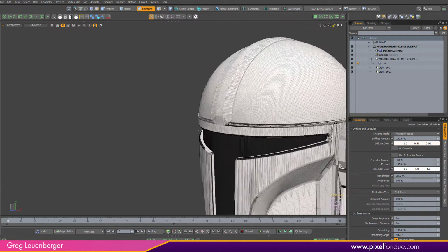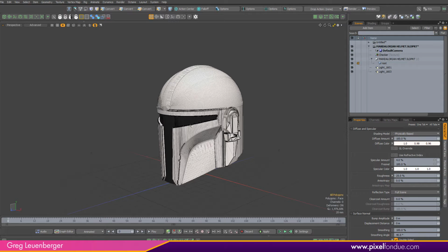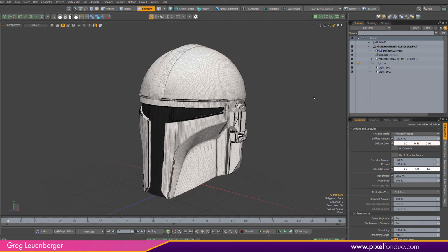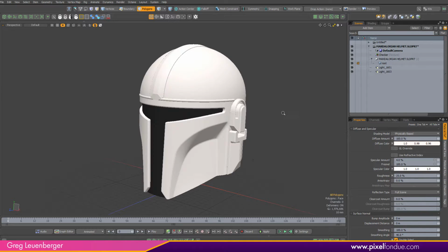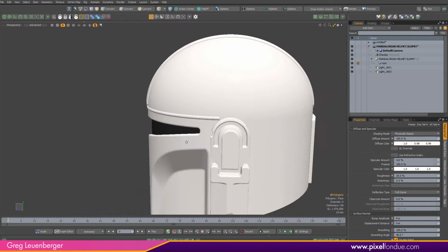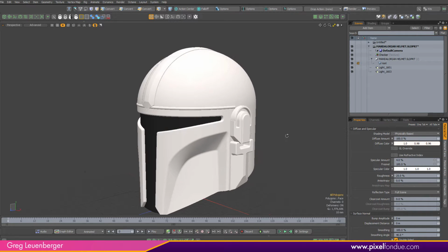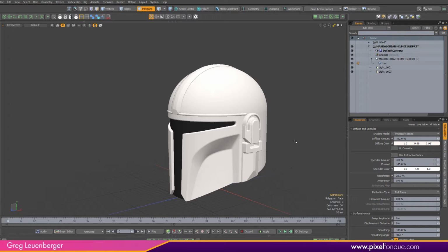So what this is, the SolidWorks part here, these polygons, where this geometry is coming from, is the OpenGL tessellated solid surfaces that are being displayed in SolidWorks' OpenGL view. And so if you have somebody with a decent computer and they have their OpenGL view set to a pretty high tessellation to have these things look pretty good in the viewport, you're going to get a lot of polygons that's going to look good. If they maybe work on a laptop and they have their OpenGL settings set to low and the tessellation set to low, you're going to get kind of crappy, jaggedy objects with not a lot of polygons. And that's just how that works. It's a free importer, it comes with it, but there's not a lot of control.